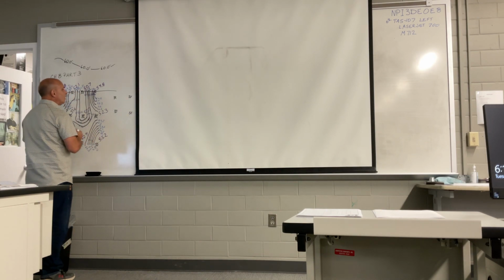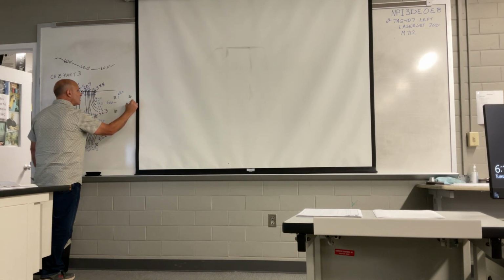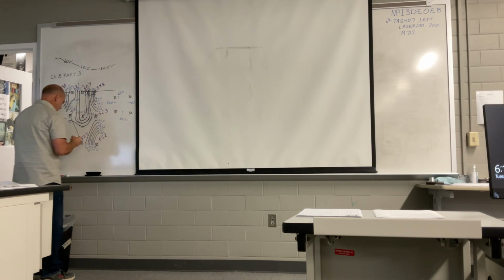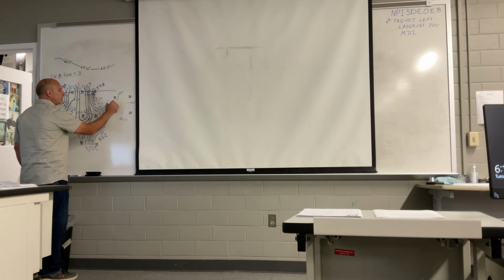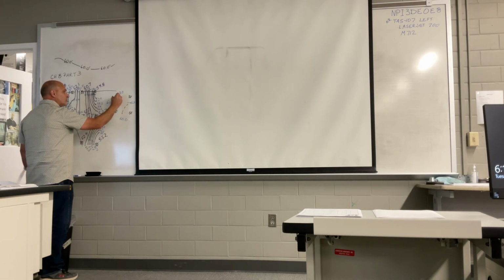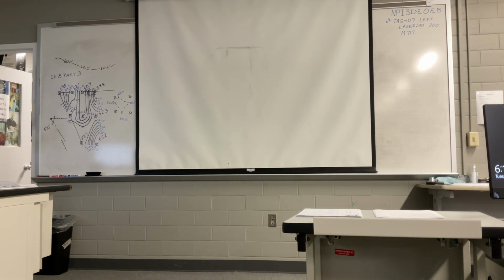So maybe we went through and did our tick marks, and here was a 60.0, here was a 60.0, here was a 60.0, here was a 60.0. If you come to this and it doesn't look obvious, does your contour need to go here to here? Or does your contour need to go there to there? Lots of times what you need to do is just step away from that box. Go pick another area and work your way back to it from your other areas.